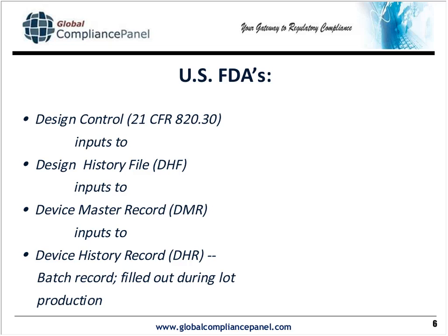And then, of course, the device master record, part of it includes an unfilled template that is your traveler, usually your device history record, DHR, or batch record or lot record or serial number record that goes along with the product as it's being built to record lot numbers of raw materials, steps that were taken, QC that was performed, individuals that did it, times it was done, parameters set on various key pieces of equipment, etc.